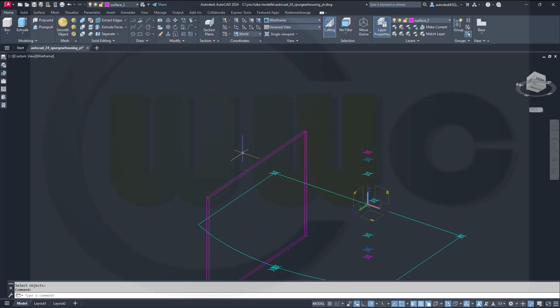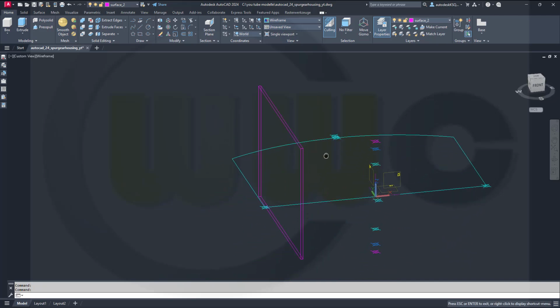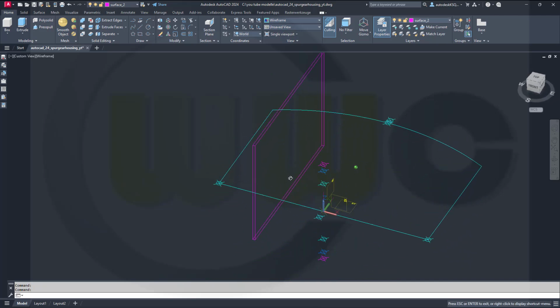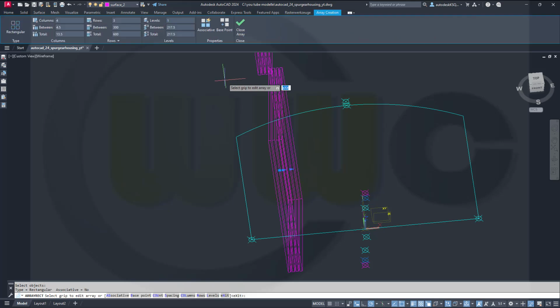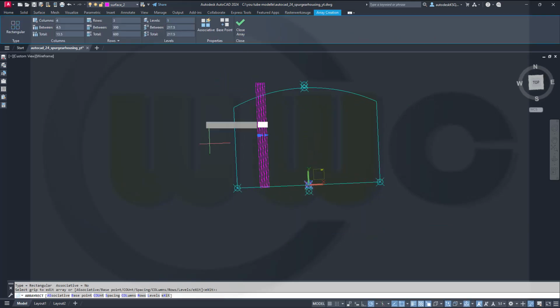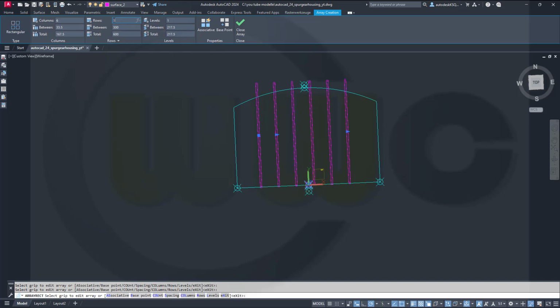Just confirm this. Great. Then I need a pattern, a rectangular or linear pattern. Yes, that should work. So where's my pattern command? There you go. Or array command. I want to pattern this one. Right click. And it should go to the X direction. Yes, I need 6 instances, and the distance between them should be 33.5, and just one row.